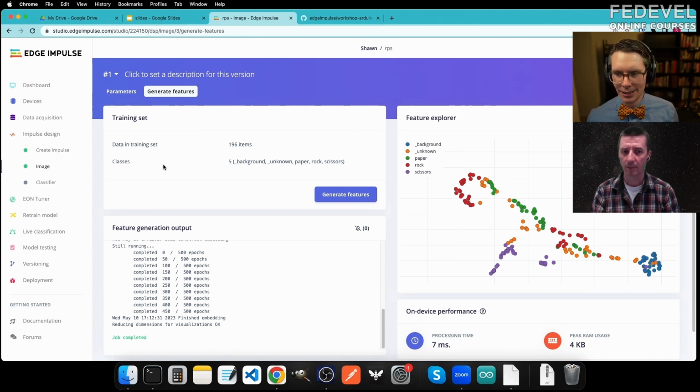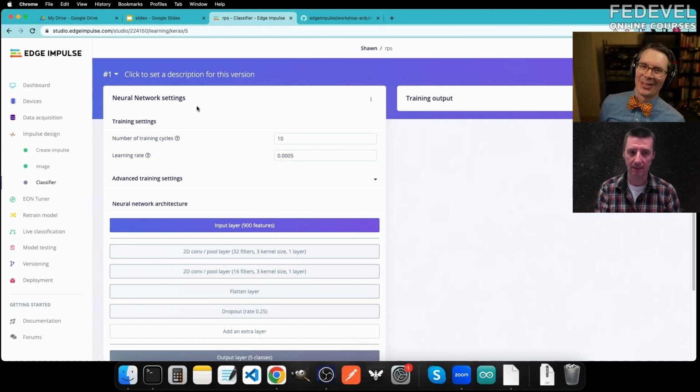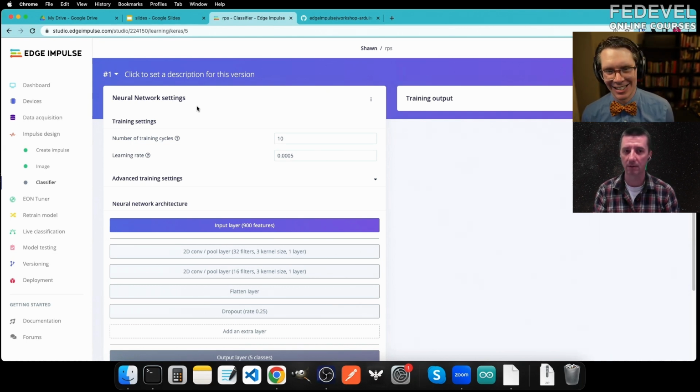So basically, if you would be using, let's say, the Fourier transformation in this learning process, you also have to use it on the board when you will be converting the real data and accessing this model. Yes. Anything you do here, you have to do on your board if you want it to work locally. That is very important to remember. Any transforms you do prior to that machine learning model, if you do an FFT, you've got to do an FFT on your board. Sometimes I've seen it where computing the FFT is more computationally expensive than the neural network. So keep that in mind.